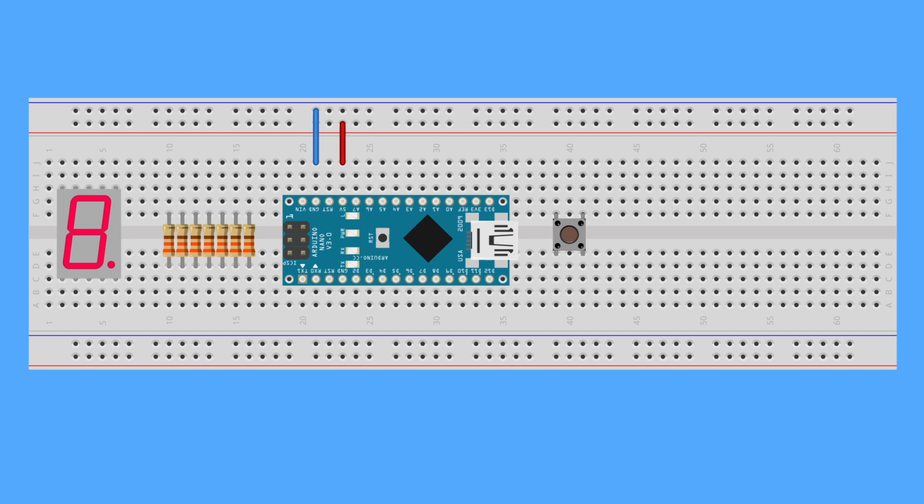The first thing to do is to connect the power rails on the sides of the breadboard to the GND and 5V lines of the Arduino. Now we can power the display through its central pins. The model I'm using is a common anode, so I connect the central pins to the positive rails. If you use a common cathode model, the central pins must be connected to the GND rail. In addition, you will have to do a little modification in the sketch.